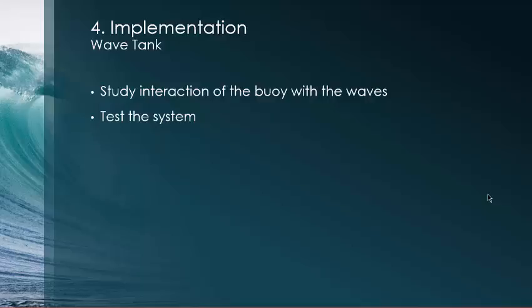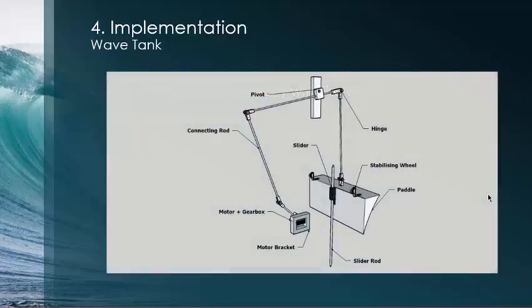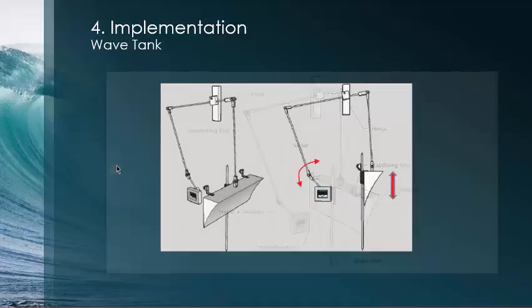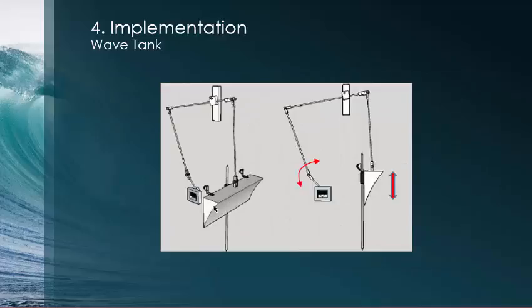The wave generation mechanism was designed as follows, with the different parts shown. The paddle, the component in white here, is hollow and impervious and is made from composite aluminum sheets bonded together with a silicone adhesive. The paddle pushes the water forward by moving up and down, thereby generating waves. This up and down motion is called reciprocating motion.